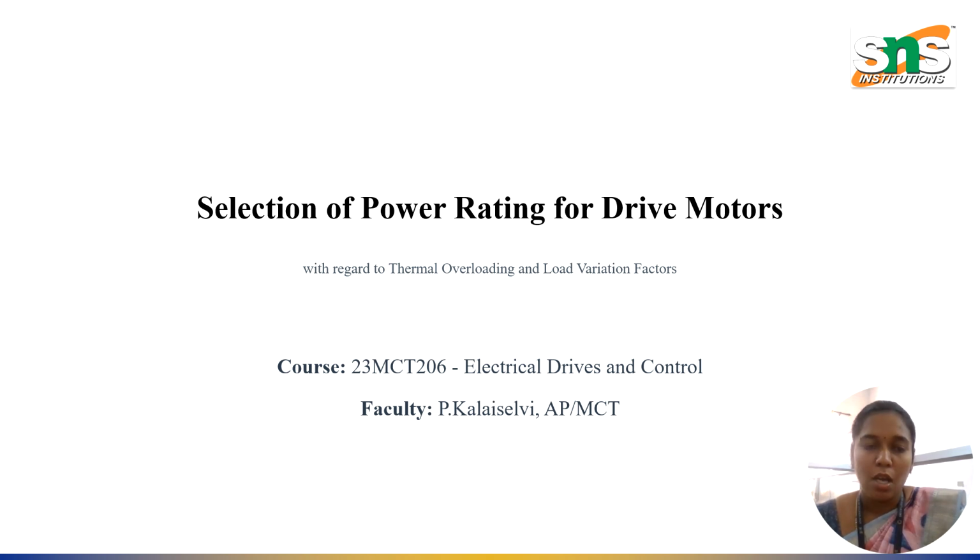Today we will discuss a very important practical topic, that is, the selection of power rating for drive motors. In electrical drives, selecting the correct motor rating is critical. Why? Because an underrated motor leads to overheating or failure, and an overrated motor means unnecessary cost and poor efficiency. So our goal is to choose the optimum power rating considering the thermal and load factors.